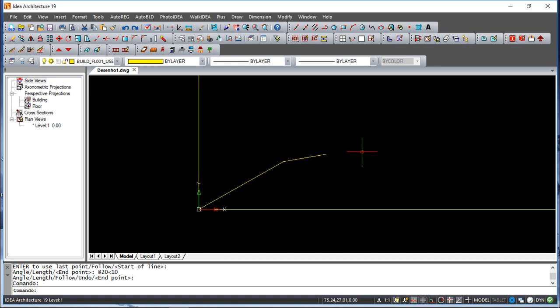And we can also have something called UCS, which are user coordinate systems, which we can have for temporary work. So if I create one user coordinate system, I can place it somewhere and I can work in the exact same way as I've done here, and it will be the origin for this temporary system.